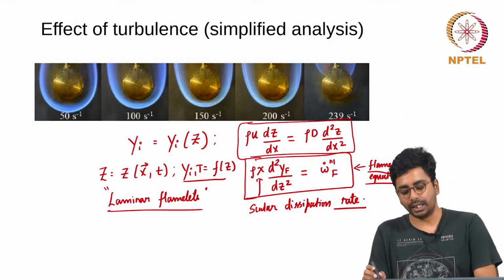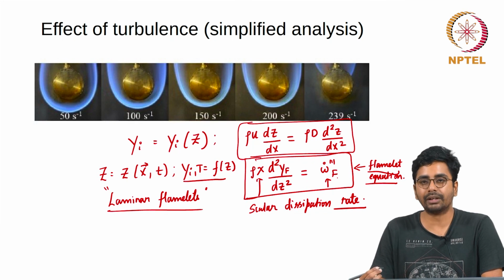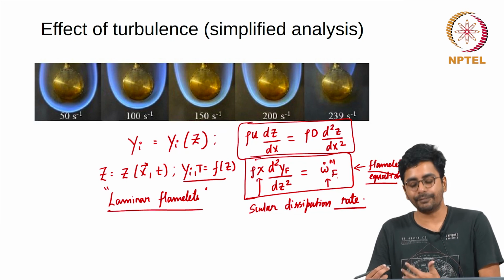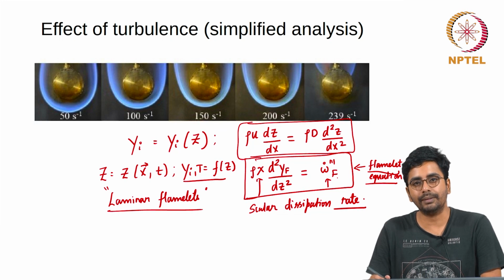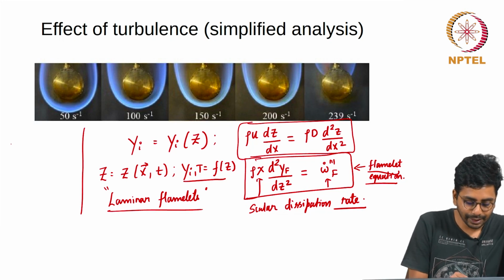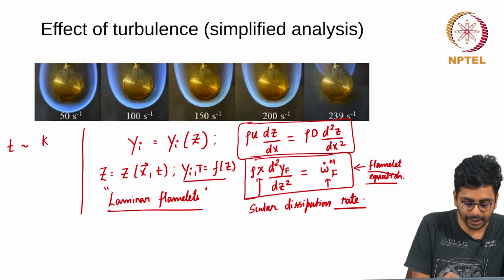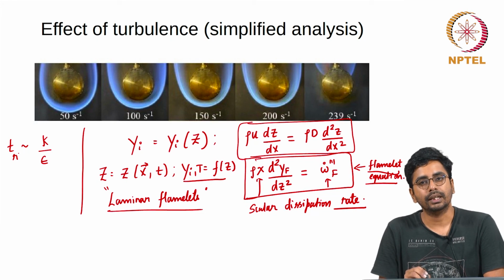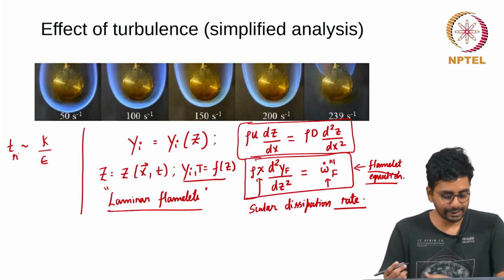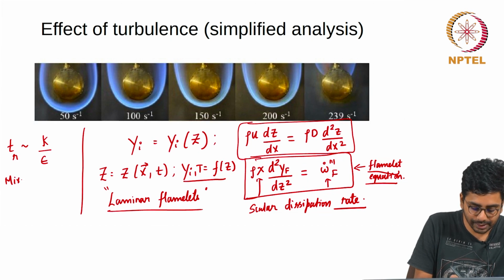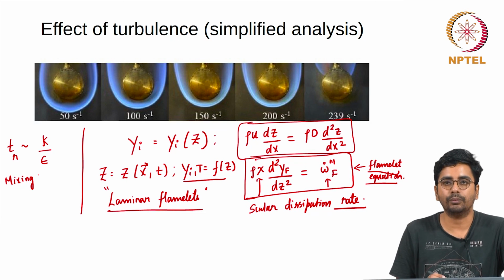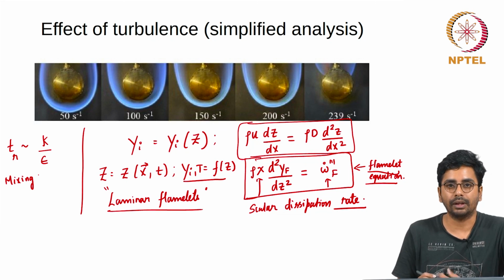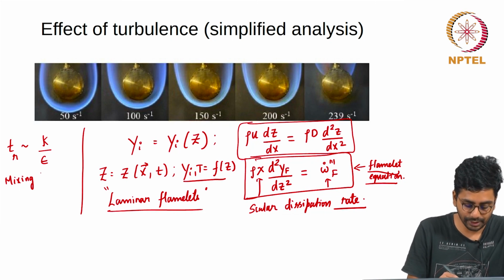In fact, further simplification is also possible. If the chemical reaction rate can be assumed to be infinitely fast, then the flame is completely controlled by the mixing rate, and the mixing rate can be calculated from the turbulence quantities. The reaction rate can be taken to be equal to the time scale of mixing because of turbulence, and these mixing controlled models are very useful in getting a first cut picture of what is happening in a non-premixed turbulent combustion chamber.